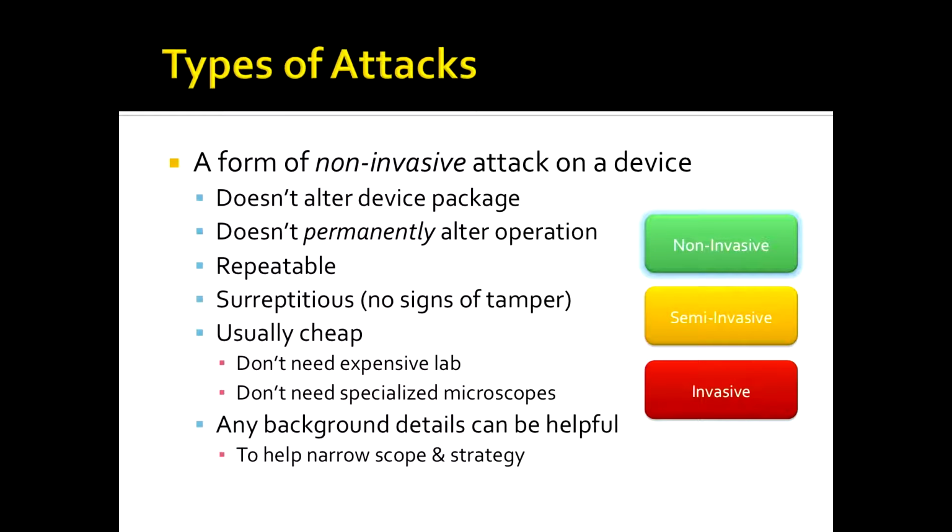Another fairly important characteristic is that non-invasive attacks are usually cheap, so you don't need an expensive lab, and you usually don't need specialized microscopes or other expensive tools. The drawback to the non-invasive attack is that any background details you have beforehand are very helpful because they help narrow the scope and the strategy you want to use when glitching, rather than a completely black box device where you have no idea where to start. You could take many wrong turns, so any information you have beforehand would be quite helpful.